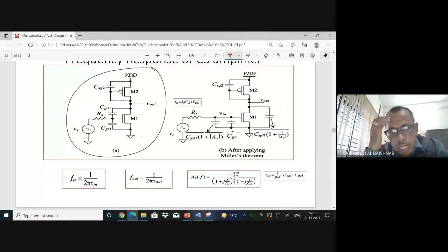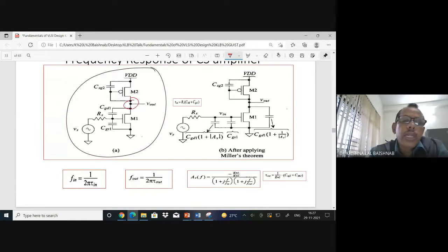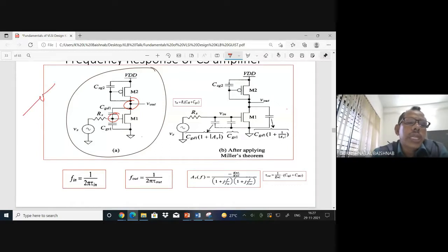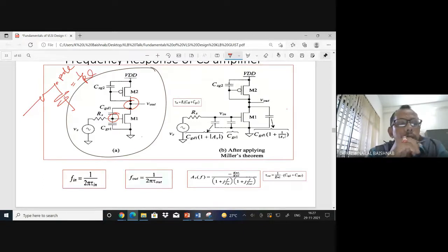Now you see what they have designed in this circuit. If I look into the circuit, I can easily say it has two poles. One pole is over here, another pole is over here. Pole means wherever a resistance and capacitor meet, that gives one pole, 1 by RC. What I studied in control, 1 by RC, or 2 pi RC.